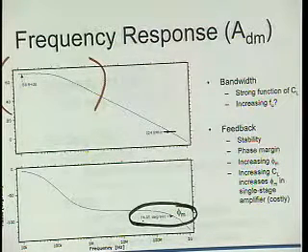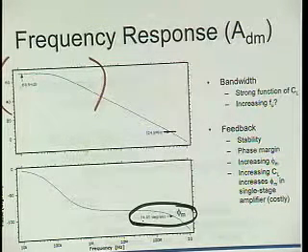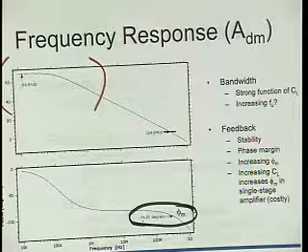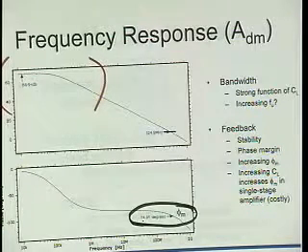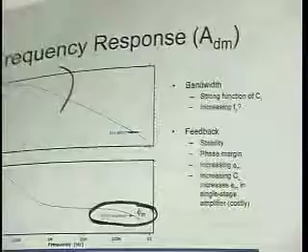First of all, most amplifiers you buy off the shelf are compensated to be unity gain stable. Why? Well, because people figure that if you use the amplifier, you probably don't want to make it an attenuator or so, or actually, how could you even, right? So if it's stable for unity gain, it probably will also be stable in your case where you want a gain of 5 or so, right? But you got to be careful.